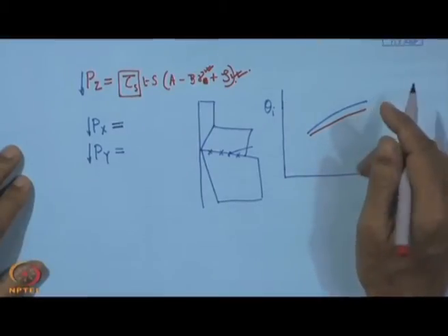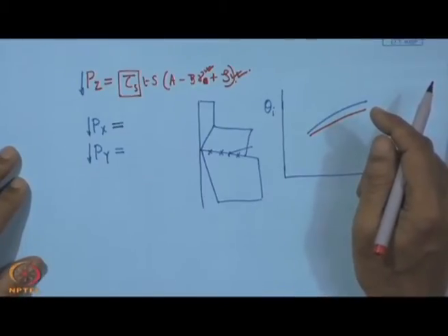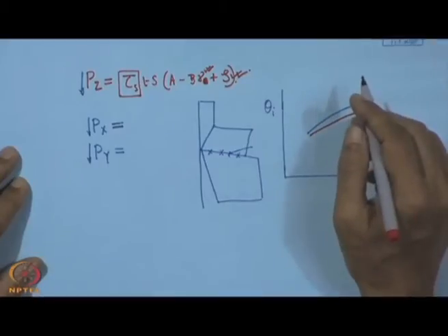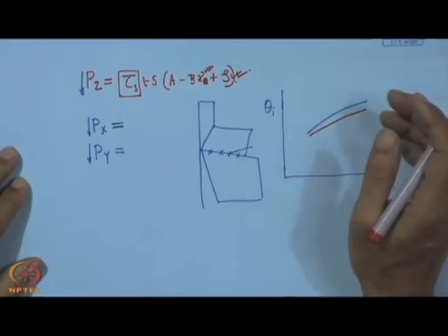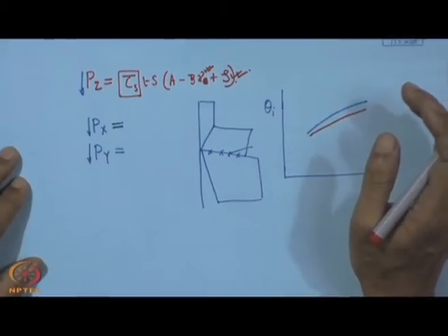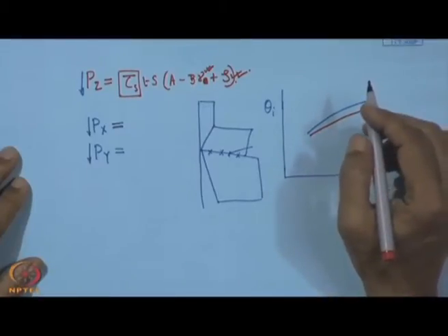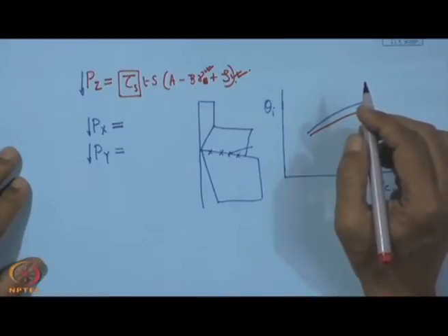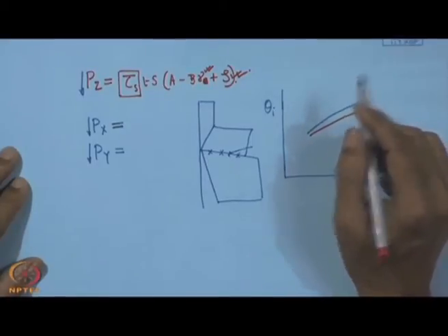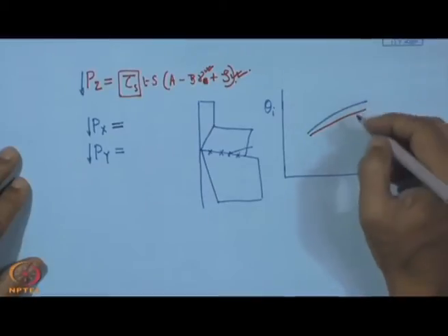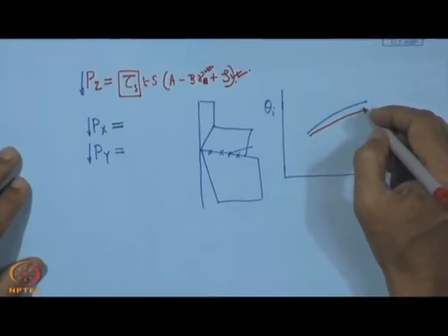So, we can also say that measurement of cutting temperature is done during the machining. So, these are all during the machining, that means cutting force measurement and cutting temperature measurement can go simultaneously. However, chip thickness measurement is done just after machining, but it can be done along with measurement of force.